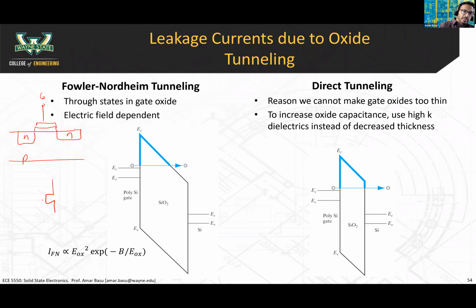And this is the circuit symbol for MOSFET device. Now, when we've talked about the modeling and how this MOSFET device works, we say that you apply a voltage between the gate and the source, and the gate acts as a capacitor. You build up a bunch of positive charge in the gate, okay, and that creates your inversion channel and so on. The key point that we made here was that the gate is like a capacitor, right?